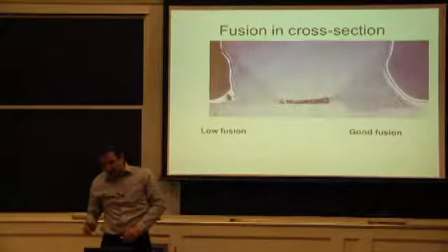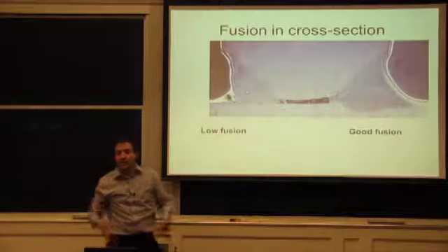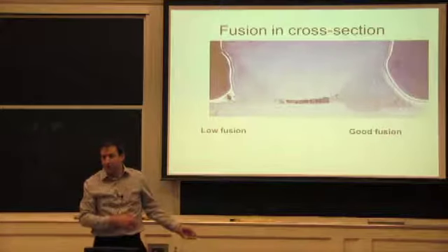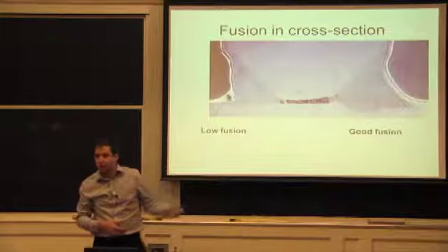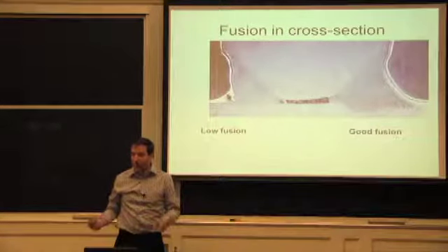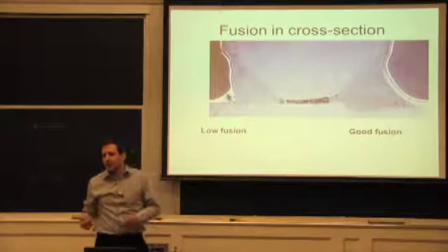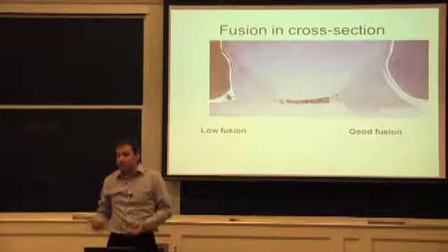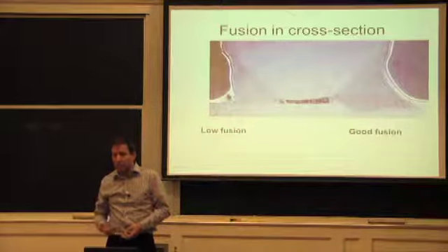If you don't have a good way to avoid a low fusion weld in, say, 1% of the time, you need to be able to live with the consequences of having one that fails. And that's where it comes in. So are you going to weld on both sides or just on one side? You could argue, I'm very unlucky if I get a bad weld on both sides. And I think it's less likely than getting it wrong just on one side.